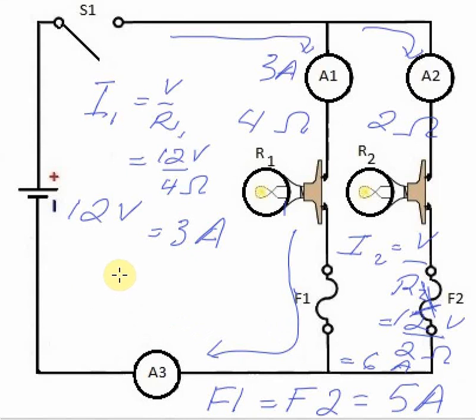So that's a parallel circuit and what can happen inside a parallel circuit. Because of the large current in the second branch, this fuse F2 ends up blowing. F1 does not. So the light here continues to stay on in this circuit. That's it for this example.